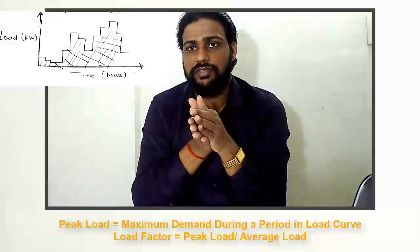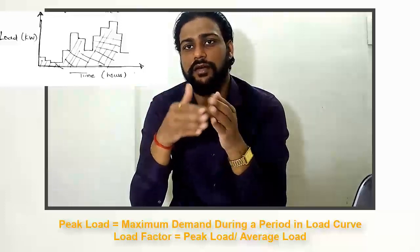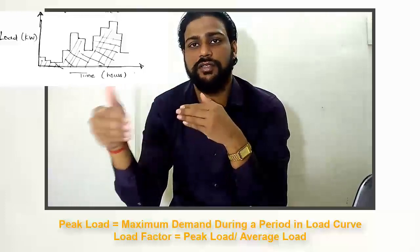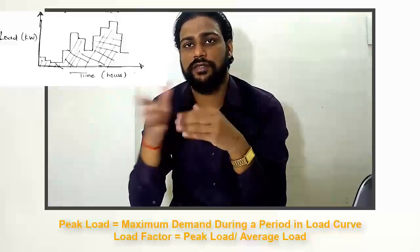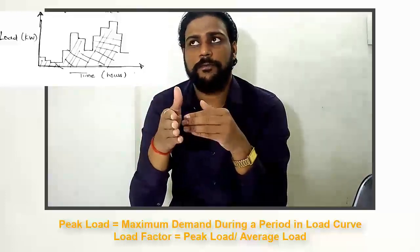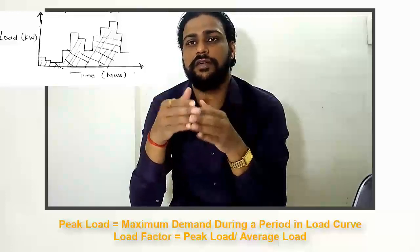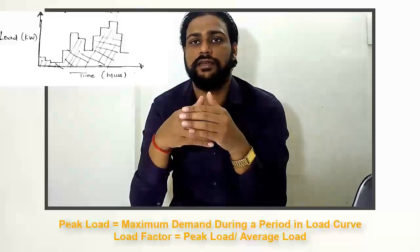But since my average load is close to 1400, I will never run my power plant to 2000 watts in this case, just a small power plant or small generator if you consider. It could be in kilowatts, it could be in megawatts for larger systems. But I would be running it close to 1500, and I would have a backup generator or a backup from the grid whenever I need that extra 500, if at all. So that was all about the load curve.